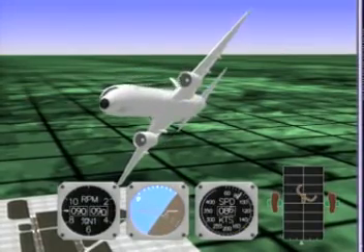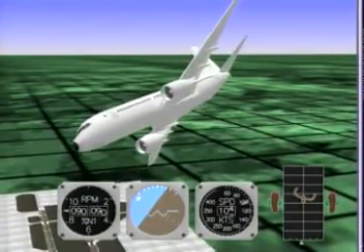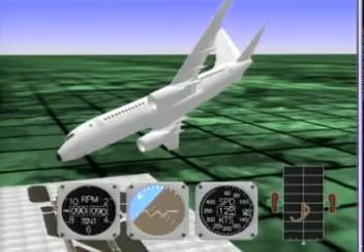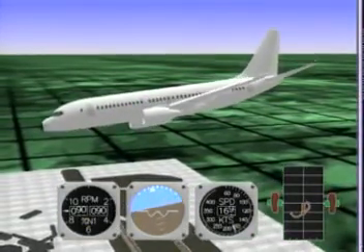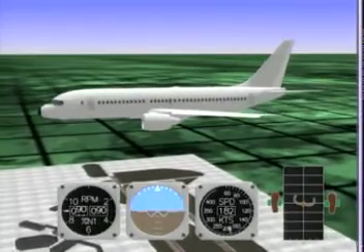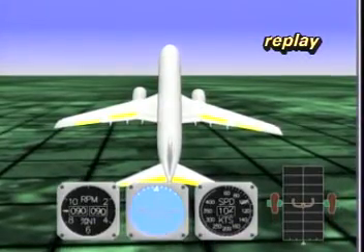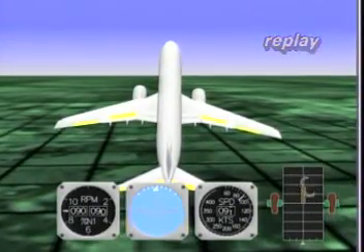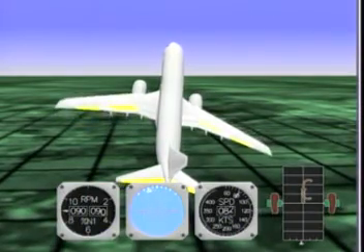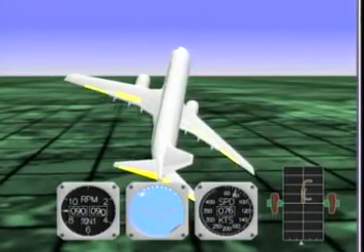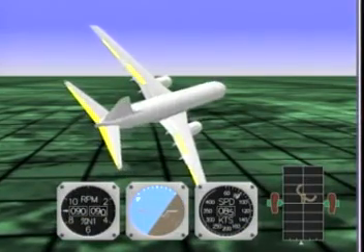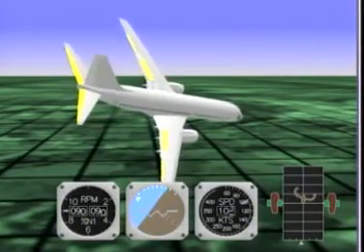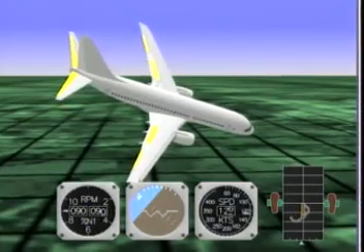Maintaining continuous nose-down elevator pressure will keep the wing angle of attack as low as possible, making the normal roll controls as effective as possible. With airspeed as low as stick shaker onset, normal roll controls up to full deflection of the ailerons and spoilers can be used. The rolling maneuver changes the pitch rate into a turning maneuver, allowing the pitch to decrease.